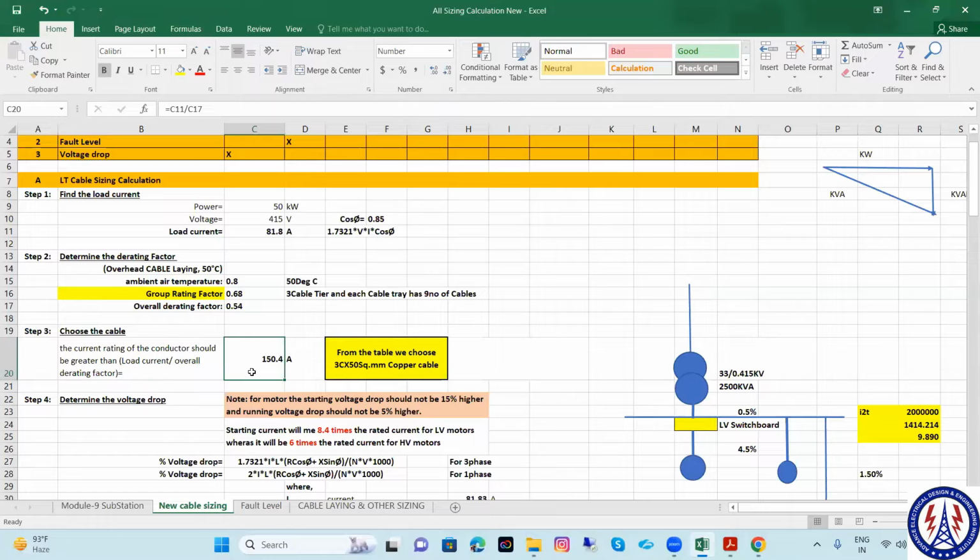Okay, so they are using the cable for taking supply to the dewatering motor, and the fourth core is for grounding purpose. Yes, that's why I am telling it's for the body earthing. It's not for supplying the current. It is purely for earthing only.